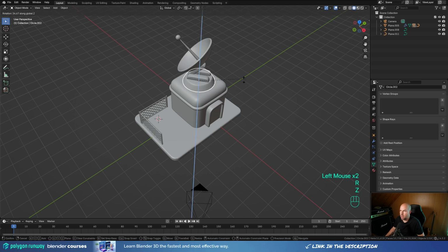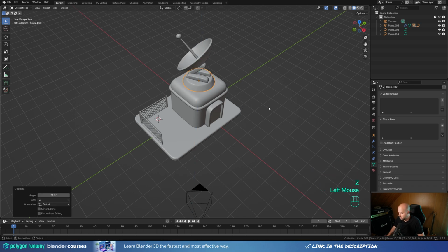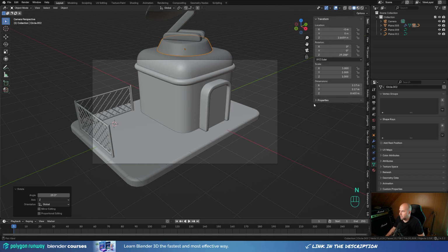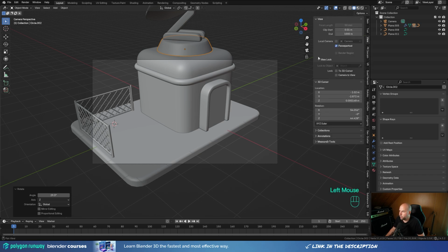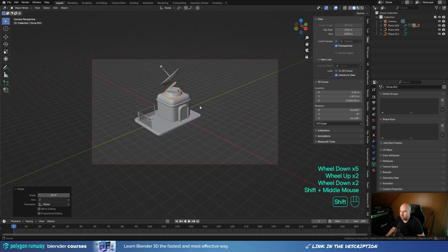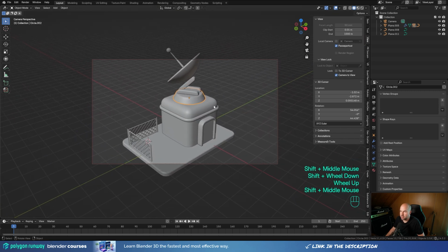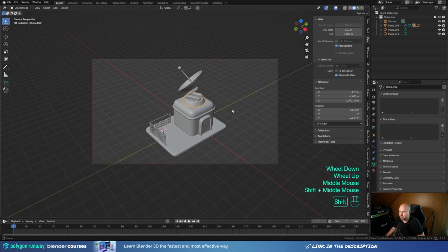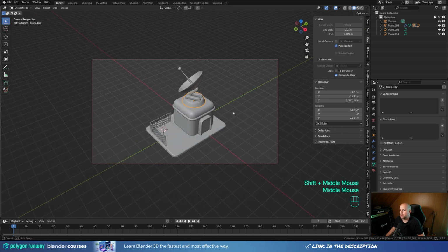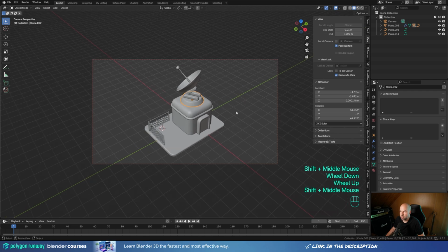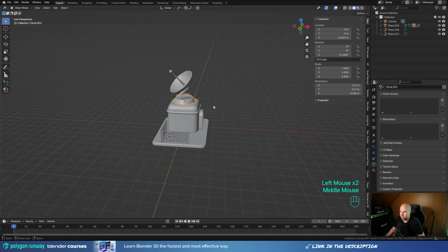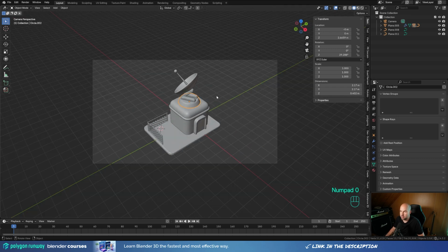Now I want to create a little bit of an animation here, so let's press 0 for camera view, let's press N for the side panel, and here we'll go view settings and enable camera to view. So now if you move your view with your standard viewport controls, you're moving camera as well. So let's find some nice position like this, for example, and we can now disable this. Don't forget to do that, because then if you would move, the camera would move as well again.